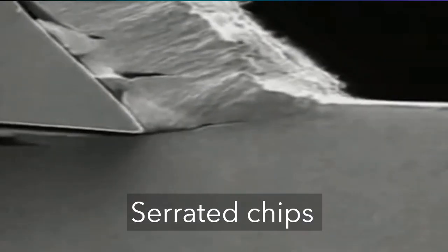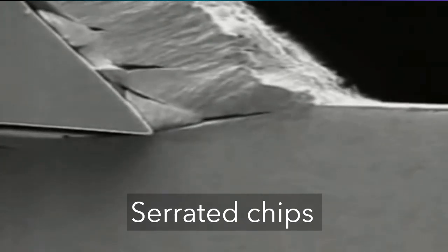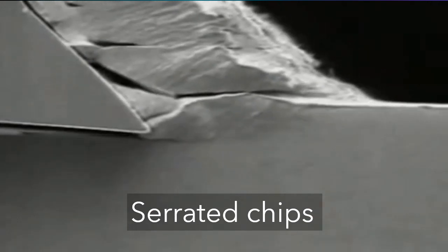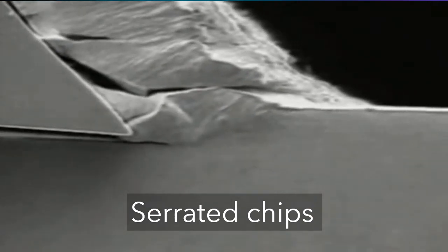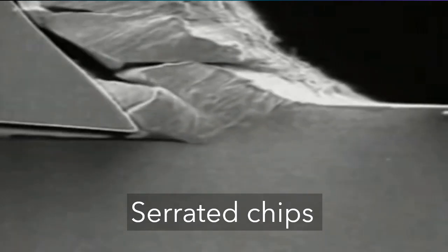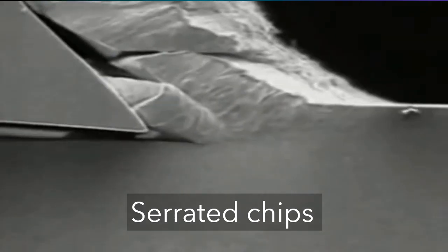Serrated chips are semi-continuous in the sense that they possess a sawtooth appearance that is produced by cyclic chip formation of alternating high shear strain followed by low shear strain.